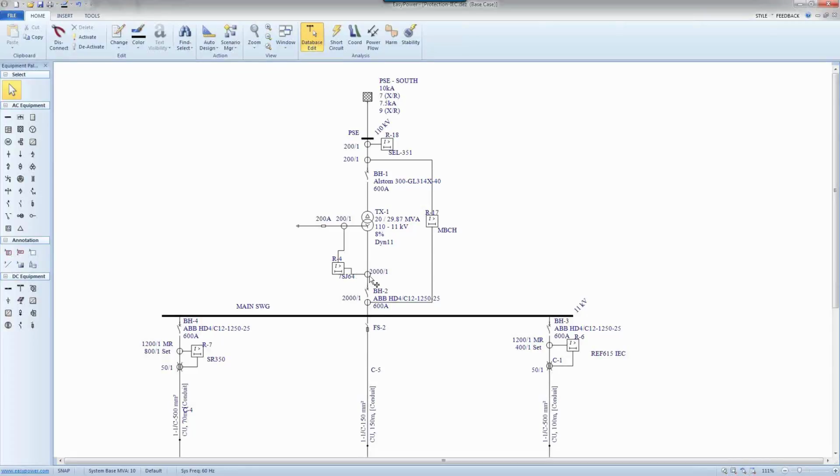numbers. For example, you would see that we have a lot of CTs with a secondary of 1 ampere, which everybody knows is not a common practice in the US. In the US, you would see a lot of 5 ampere CTs. Not that there are no 1 ampere CTs, there are, but they are not as common as in European or Middle Eastern or those areas. So we tried very hard to reach out to engineers and people who work in those areas to really hear from them and make sure that everything implemented here is compliant and is common practice in those areas.